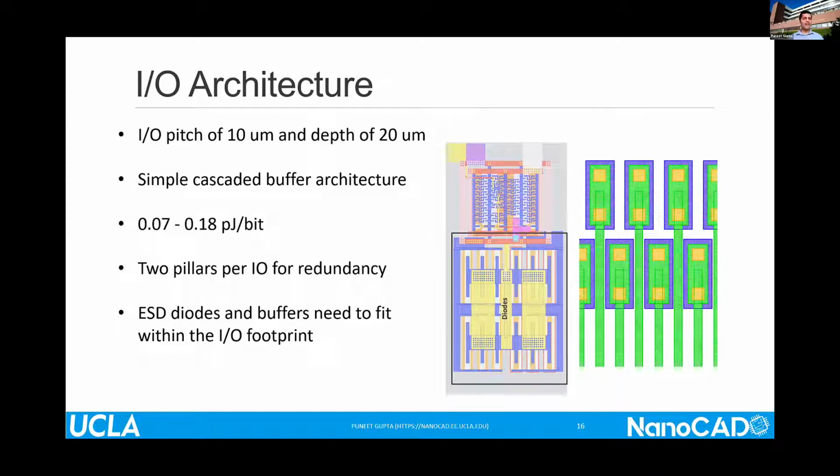And that's also where small chiplets stop making sense cost-wise after a certain point, because those overheads start to add up. If you're going to make a 1 millimeter square chiplet where you have 3 to 4 times the size of the IO, then a 100 micron dicing loss on the side, etc., it starts to add up very quickly. And that's also part of the reason why, at least from a cost point of view, we believe only large SoCs broken up into moderate to large chiplets is where the sweet spot would be, probably.